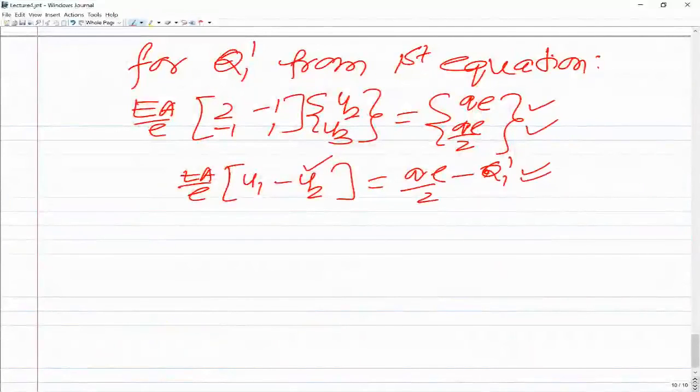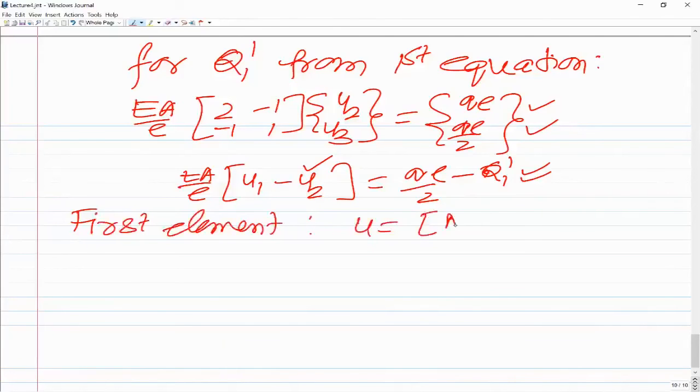And once you have solved for U1, U2 and U3, and then you want U anywhere within the element, for the first element, U anywhere within the element is going to be n1 n2 into u1 u2. u1 is 0 and u2 you would have solved, so you can get U anywhere within the element.